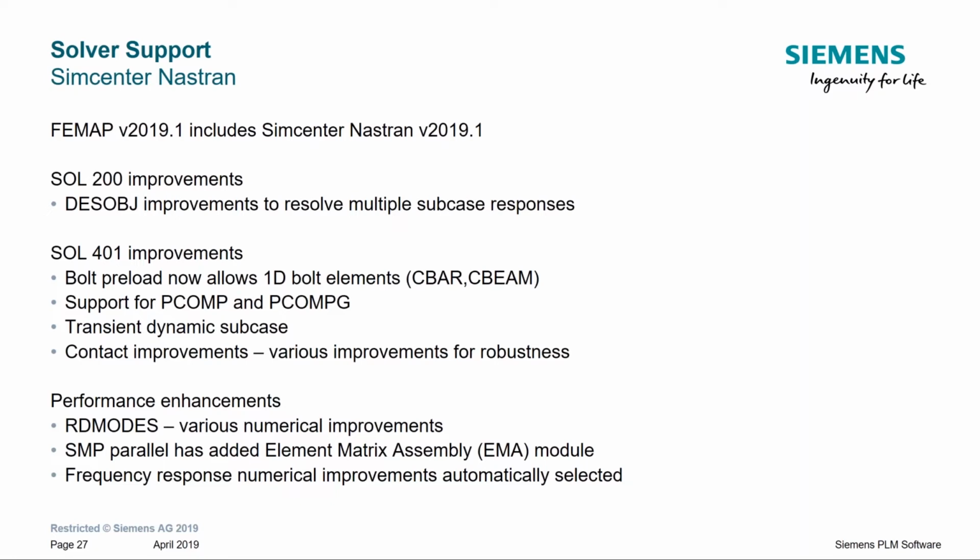So we're now allowing the bolt preload that allows the 1D bolt elements. Previously, we only could have solid preload bolt elements. We're also supporting the PCOMP and PCOMP-G for solution 401. We've added transient dynamic response subcases for 401. And then we've also done some contact improvements as well.